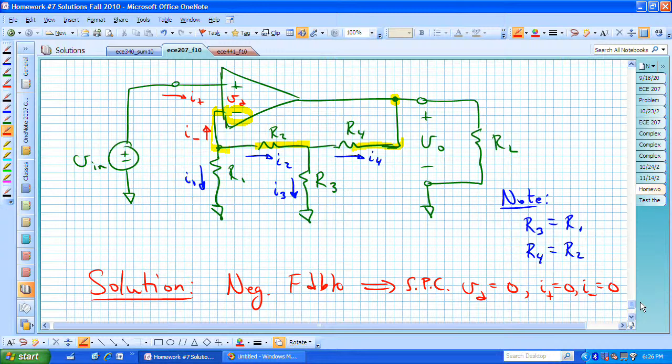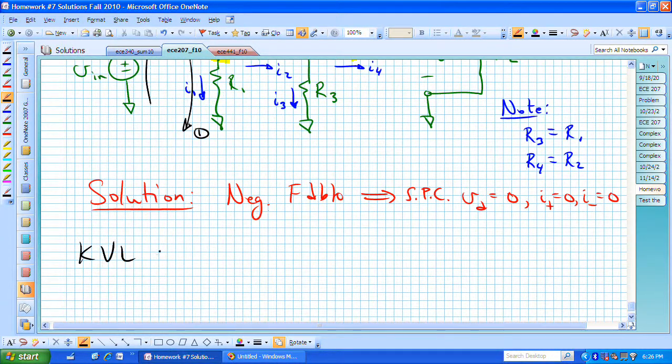We're now going to try to work our way from the input side to the output side, and we're going to drop down to ground as quickly as possible when we can so that we don't get too many unknown variables in all of our equations. Let's start by doing a KVL around that particular loop, which I will label as 1. With KVL around 1, I have minus Vn, I'm going in the negative terminal of Vn, plus V sub D, plus R sub 1 I1, which is just Ohm's law, but that's the voltage dropped across R1 from top to bottom. That's equal to 0.